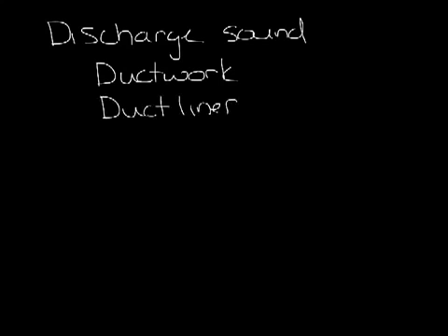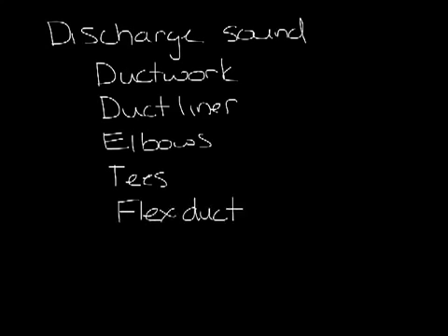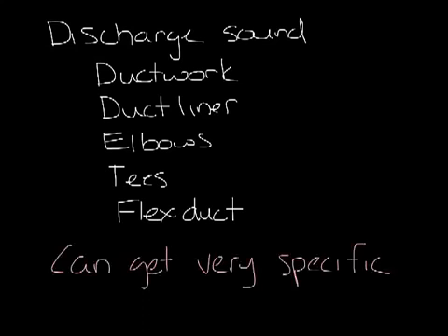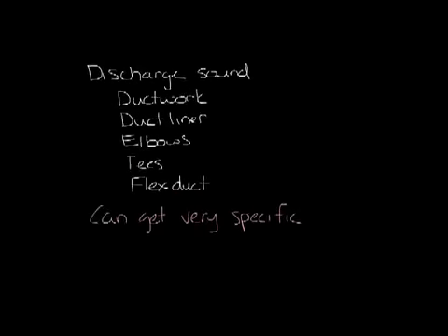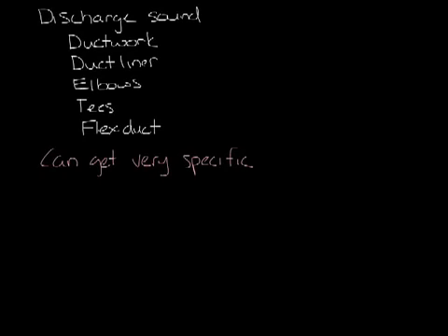Now you can basically do the same thing for discharge sound. There's just a lot more attenuation factors involved. You can have ductworks, there's tables for square and round, lined and unlined, elbows, T's, flex duct, and many other tables. You can get really specific about your application. Now you probably don't need this for every project, but there's sometimes when it is important.